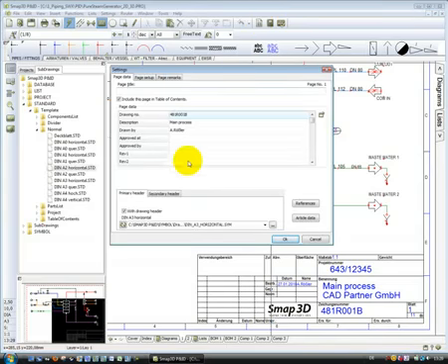Here it is also possible to create your own list with the required data fields that are included in this mask and that can be filled by the user with values, and if required such a field can be linked in the drawing header so that the drawing header will be automatically filled with information by typing the properties in these masks.